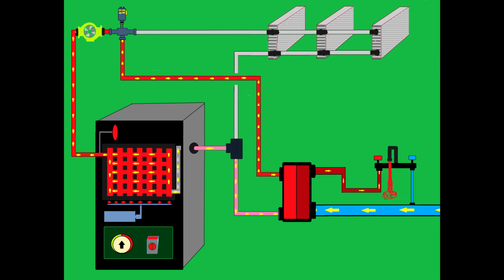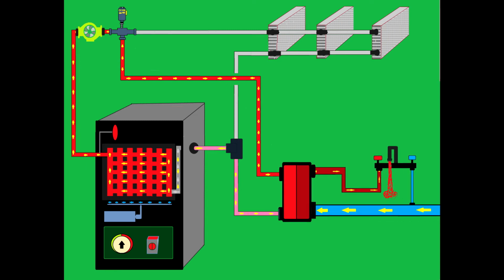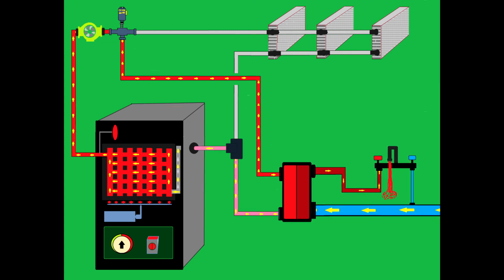You can have flow magnetic switches, and there's all sort of things. They have to be studied individually, and I will dedicate a full video for these controls. But now what is important for you to understand: anytime you open the domestic hot water, the entire flow will be redirected to the plate heat exchanger, and then the heating agent will not go through the radiators.